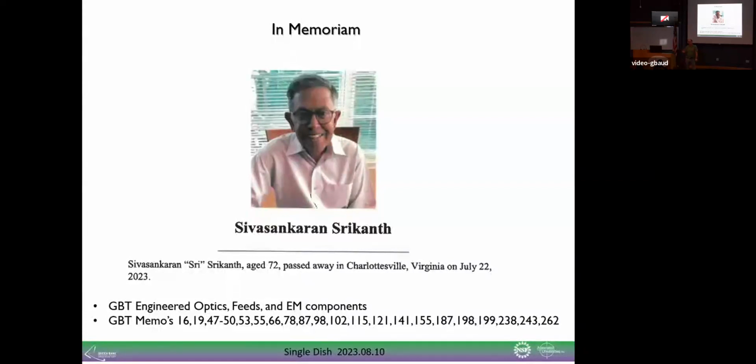It relaxes the amount of noise that your follow-up amplifiers have, so it makes the design a little bit easier. Nowadays, follow-up amplifiers are pretty low noise temperature. I mean, they're making room temperature amplifiers now below 100 Kelvin. So divide 100 Kelvin by 2000, and there's hardly any contribution from the warm electronics.